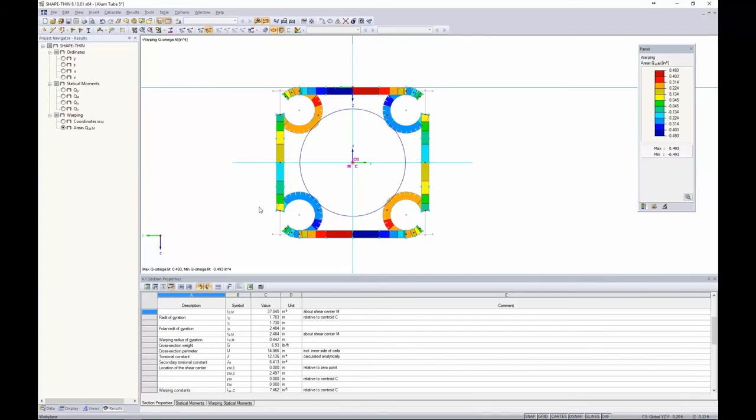And that's because I need to implement these C sub T elements within the shape thin. And C sub T elements are just width to thickness ratios. Now, in order to implement C sub T elements, they can only be added to these straight line segments here. They cannot be added to these arcs. So if I was concerned with local buckling of one of these arcs, or had some other different shape where I had a rather large arc that I'd like to check local buckling, then it's suggested that you create multiple straight lines that compose that arc, and then you can create the C sub T elements.